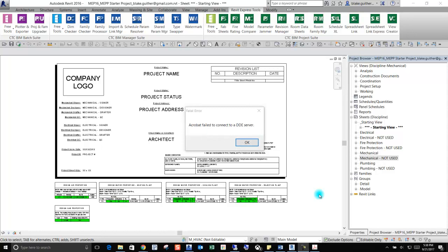However, they ended up getting a little long, and in some cases that made it difficult for users to see what the parameter was in the Revit project environment. So not only should they be easily understood, but they should be short enough to be visible in any particular window. We want to keep units out of names so that we can talk about these shared parameters with people in the metric system, Europe, in Asia, and all those other places. So these are meant to be universal. And then also using some of the features in Revit, tooltips, giving users information. If we do have to abbreviate stuff, use a tooltip to indicate what the shared parameter is.